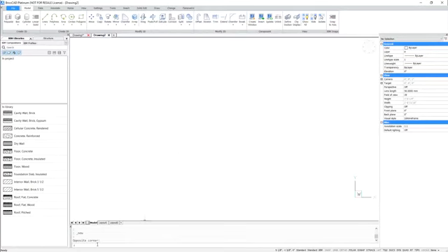So I've turned the command line back on here because I want to show you how to use BricsCAD at different trial levels. If you use the command run as trial level, you'll see you have various options. You can choose BricsCAD here. If I hit enter for BricsCAD, by default, my trial license is giving me the Platinum. That's how it's running, but you can always change this. Maybe I want to see if I can just get by with 2D design tools. So you can try C for Classic, and do notice the message that says the new level will be in use after restarting BricsCAD.